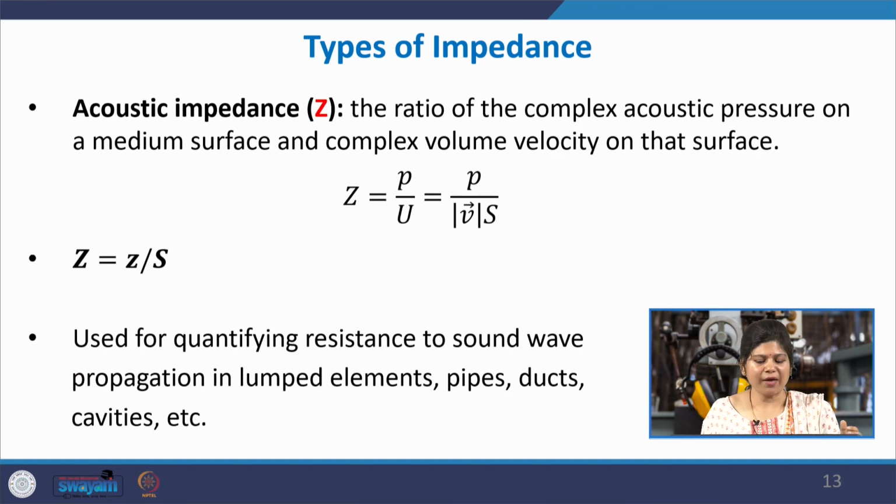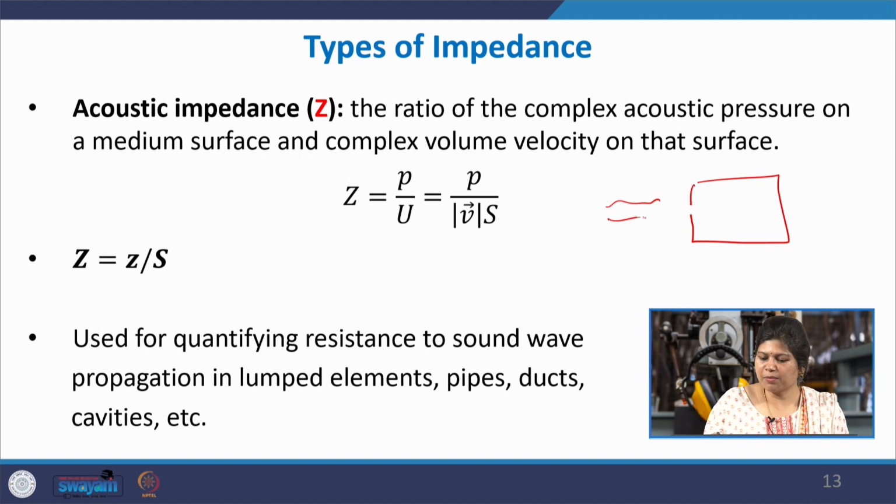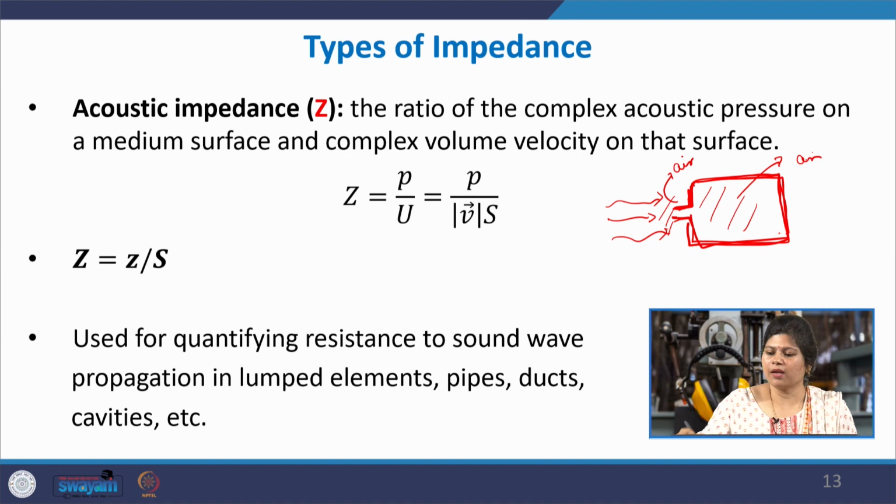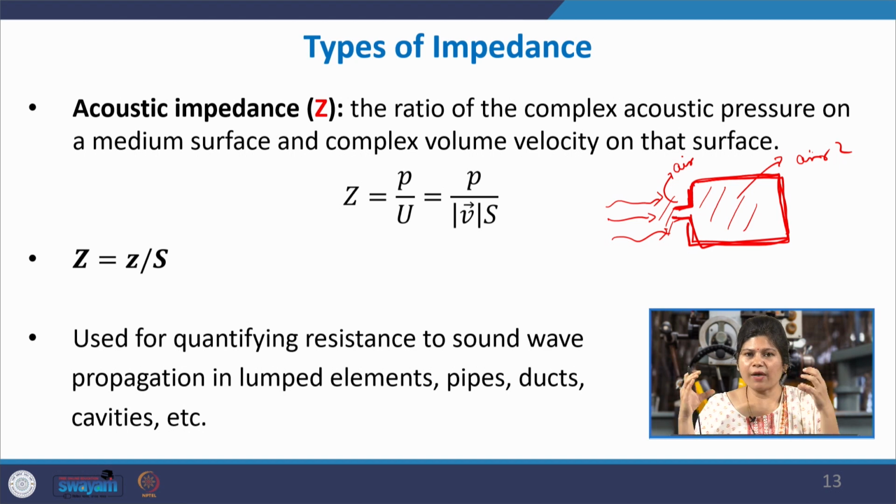But suppose the sound waves are propagating, and suddenly they encounter some kind of Helmholtz cavity. This also has the medium air, both of them have the same medium, air and air, but this air is enclosed in a narrow neck shaped cavity. So, you have a resonating element and the sound waves are incident on that.